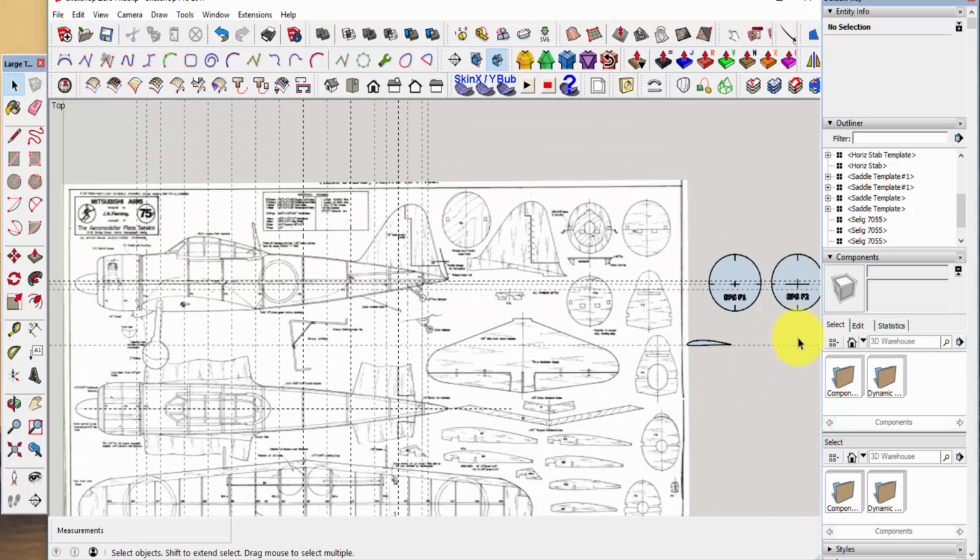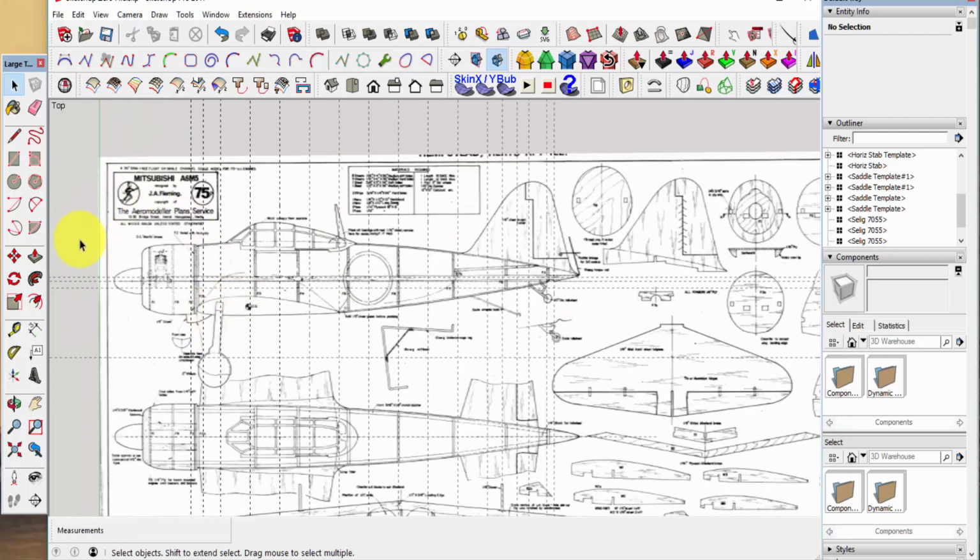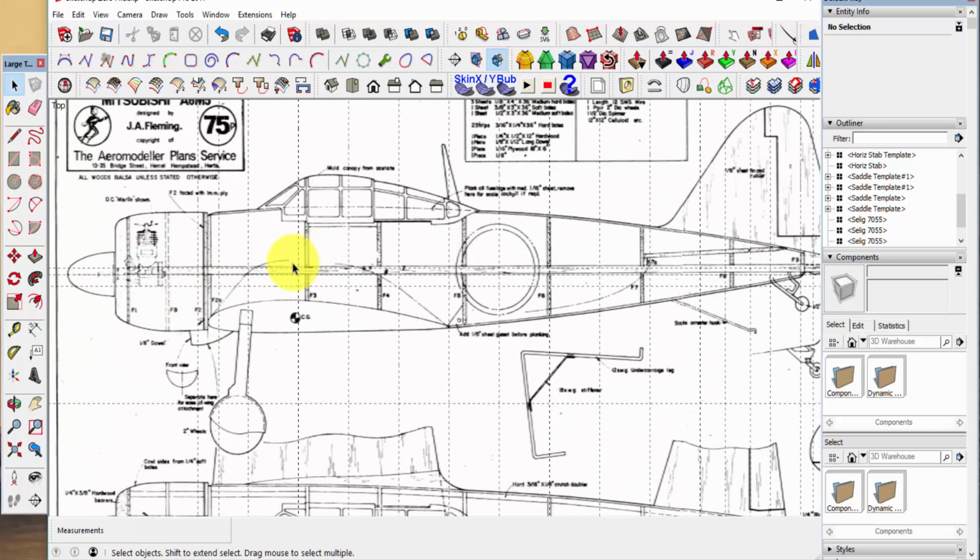Now, before we move it over here, again, this is a rudder-only model. So the designer had the wing incidence angle and the incidence angle of the horizontal stabilizer fixed for that purpose. A rudder-only plane needs to climb continuously, and then you knock it down in altitude just by doing turns. We're going to set everything up at a 0, 0 thrust line.